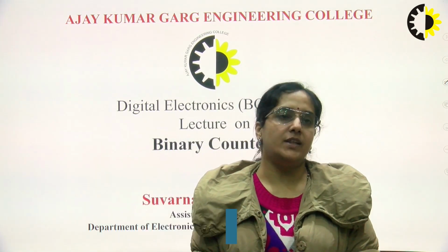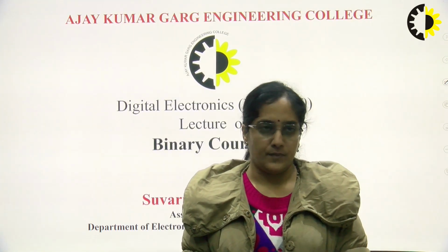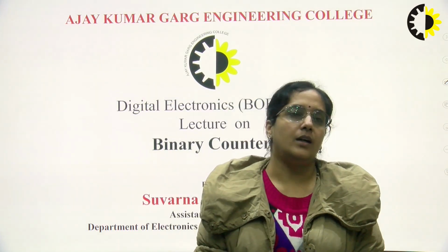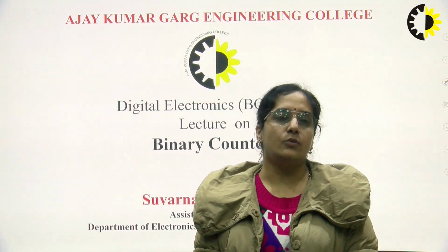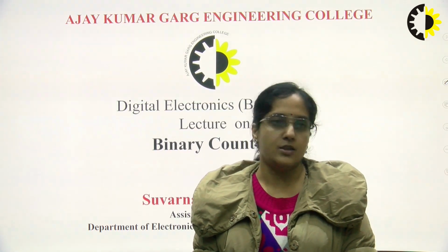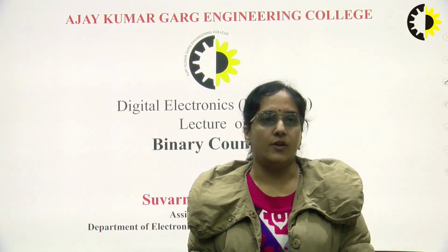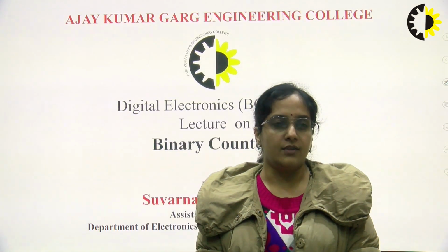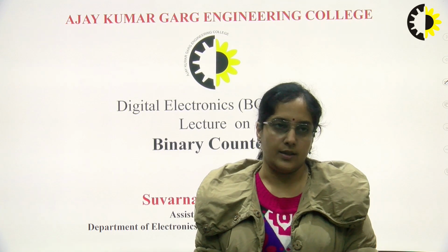First of all, we will discuss what is a counter and then how we will design this binary counter if a number system is given to us. So a counter is nothing but a digital circuit which is either asynchronous in nature or synchronous in nature, and we have both types of counters, and these counters are used to count the events that occur. So the binary counter is nothing but a group of flip flops connected in a sequence so that it can store the number of events occurred.